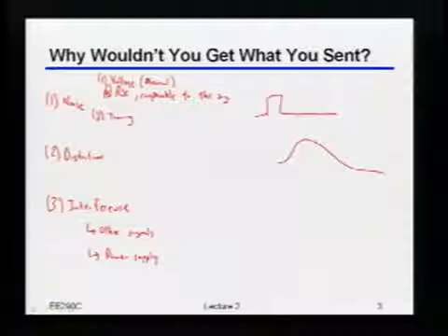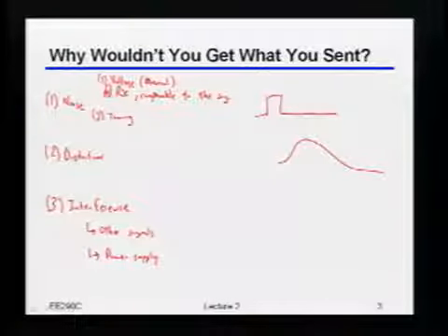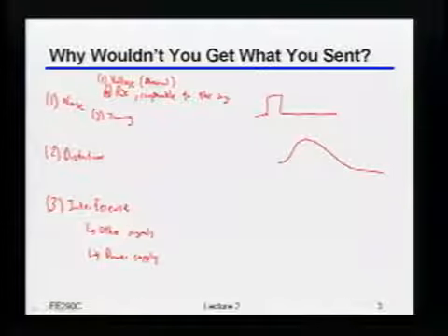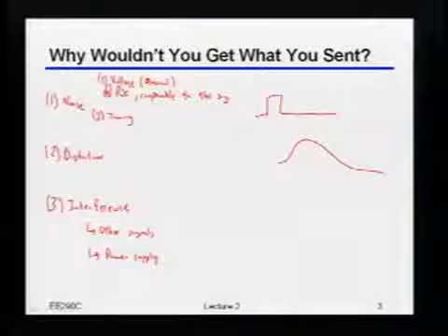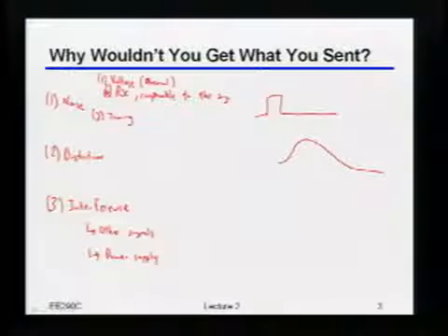Okay, now, just to be really clear, usually when people say noise and interference, they sometimes use them interchangeably, and I will probably do the same thing. But from a technical standpoint, and especially if you look at most of the definitions of people looking at signal integrity or doing performance modeling, noise really means fundamental things that are random and you can't control. Meaning you can't predict what the value actually is. It only has statistical distributions associated with it.